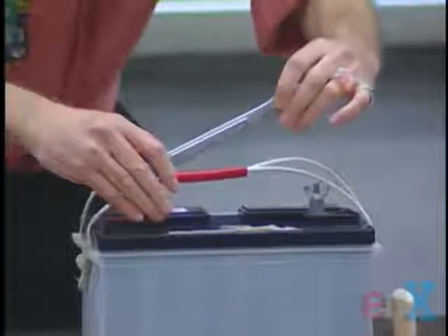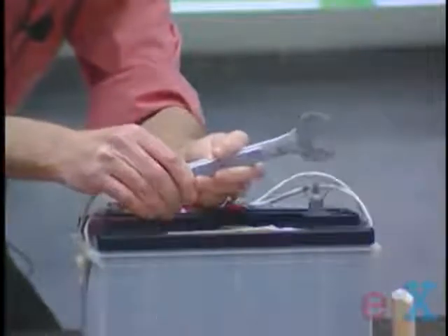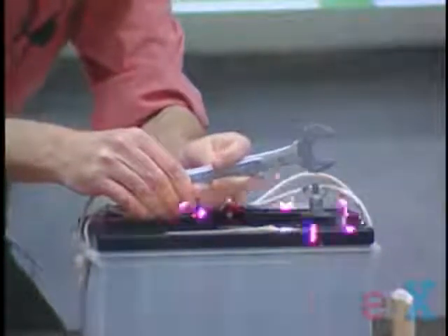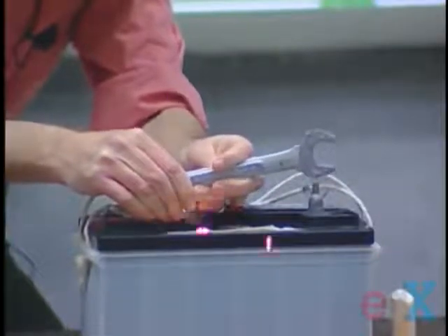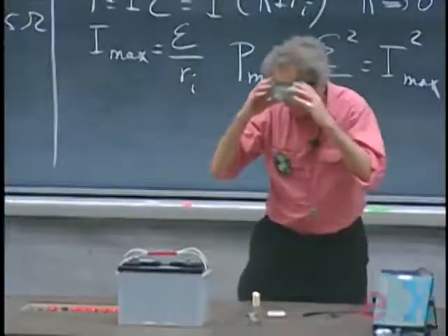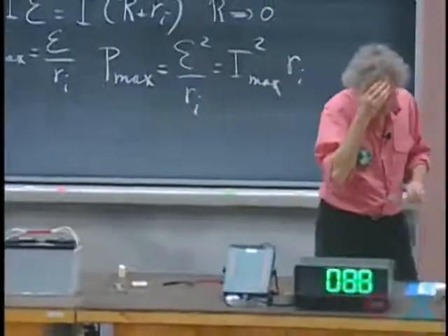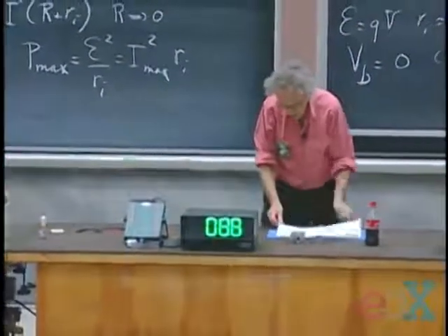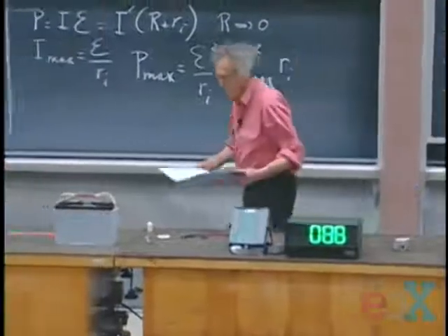You ready? Okay, I go now. You see? That's what happens. Very high current, and when you do this too often to batteries, they're not going to live very long, they don't like it. But I wasn't joking when I said that when you work on the car you should avoid this, because I have seen it happen that a wrench is actually welded onto the terminals.